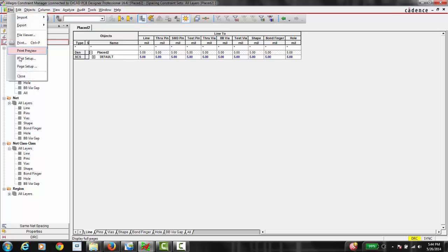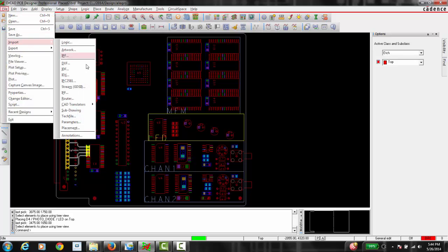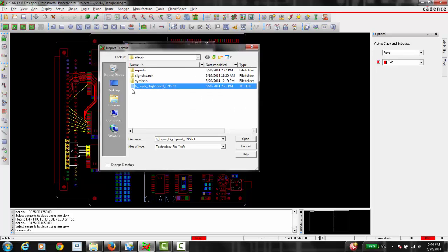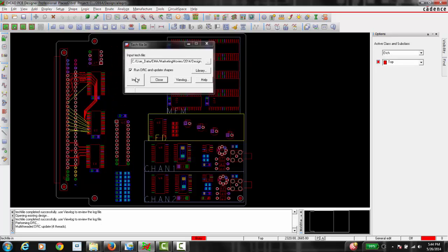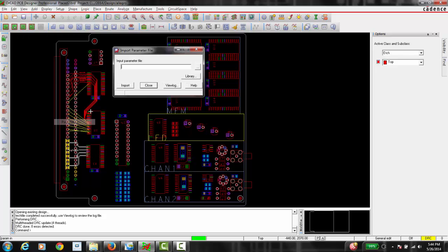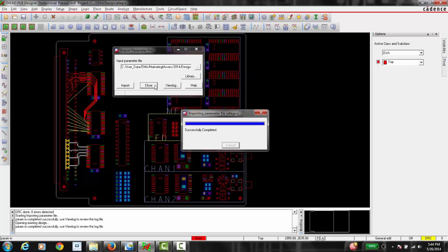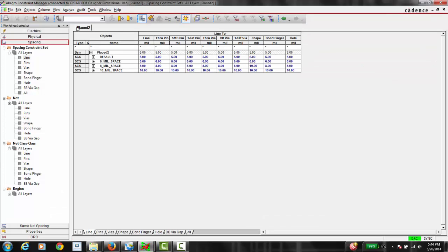We have saved off a technology file containing the constraint sets and layer StackUp from a previous design. To save time, we'll import that tech file into our placed design to quickly set up the layer StackUp and constraint sets. Once imported, we can assign those constraint sets to our nets, net classes, and differential pairs imported from our schematic.